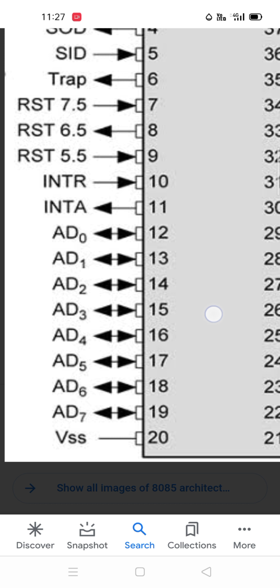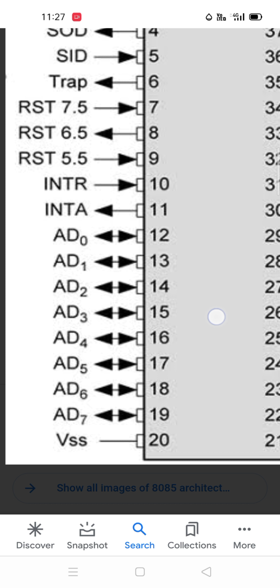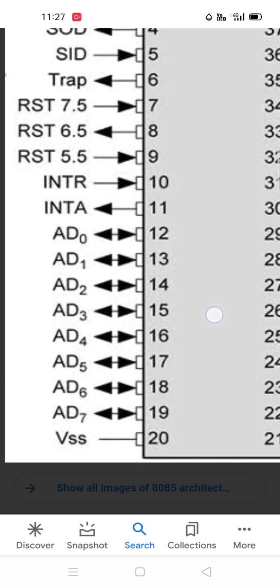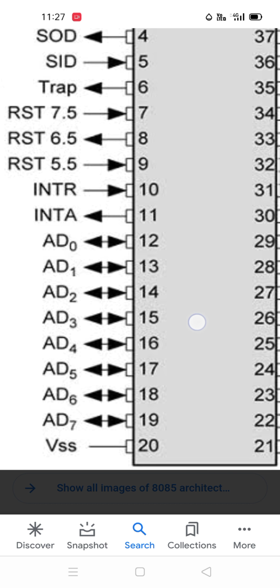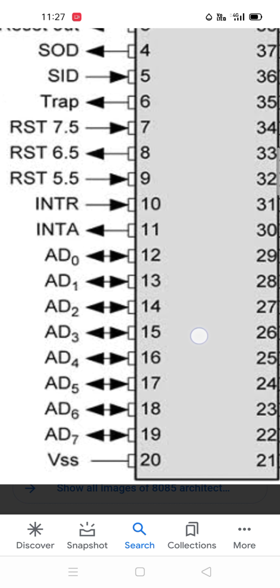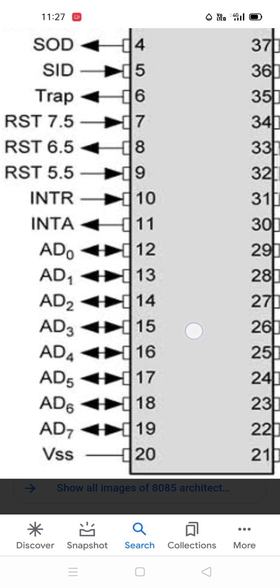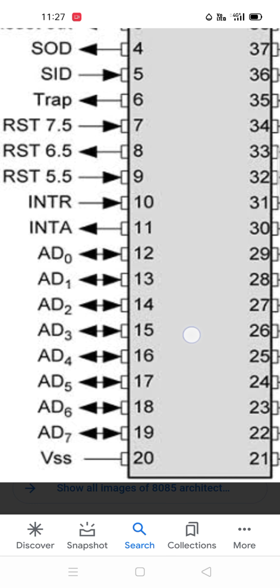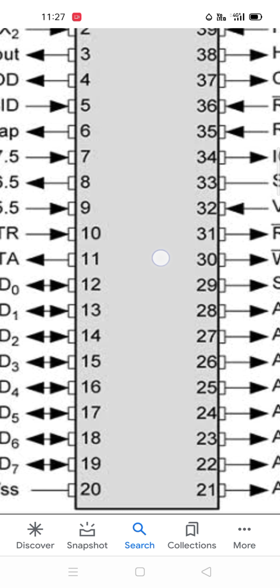Okay, and if you want to do a huge memory transfer, you cannot do it within the 8085. You have to get it into the microprocessor, transfer it to a temporary location, and from that location transfer it to the next memory location. So this cycle is very hard. So if you want to go directly from peripherals to memory or memory to peripherals, those kinds of direct access, and you just want to give away the bus access control, then you do what is called a DMA.